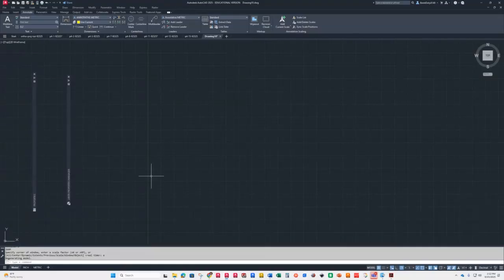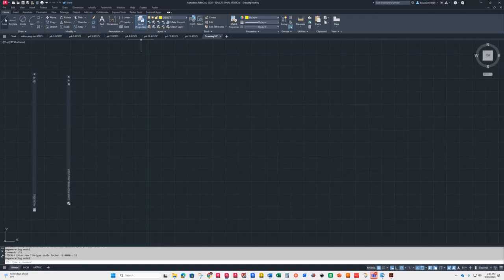So first thing I'm going to do before I start drawing is change my line type scale, and I'm going to make it 12. Probably going to have to end up making it 16 or something, but we'll see. Okay, this one's going to have a right side view. We're going to do 3 views. I'm probably going to work on the front view first and then work my way around. We're on the object view, object layer.